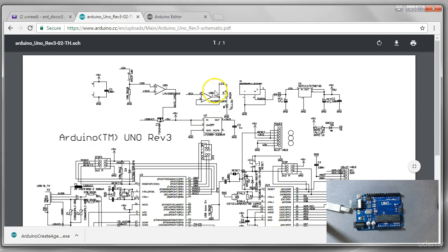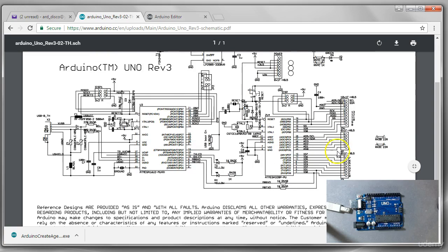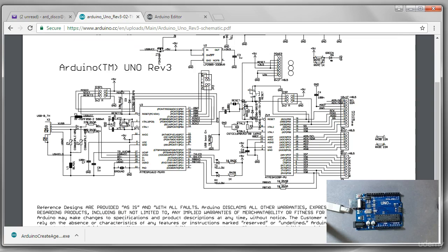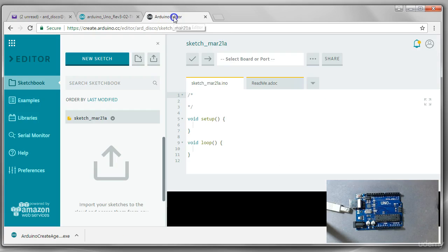And if you follow it back, it goes through this op amp, which is really just a way to connect a signal to a high drive output. And then you follow this SCK signal right there. And that happens to connect over here to this pin right here into our part. This is the big part we're programming. So SCK goes to 13 right there. So pin 13 on our board, if we were to look over here, which is right up here, actually connects to an LED, which is right there. Okay, so that's the first piece of information we are looking for.